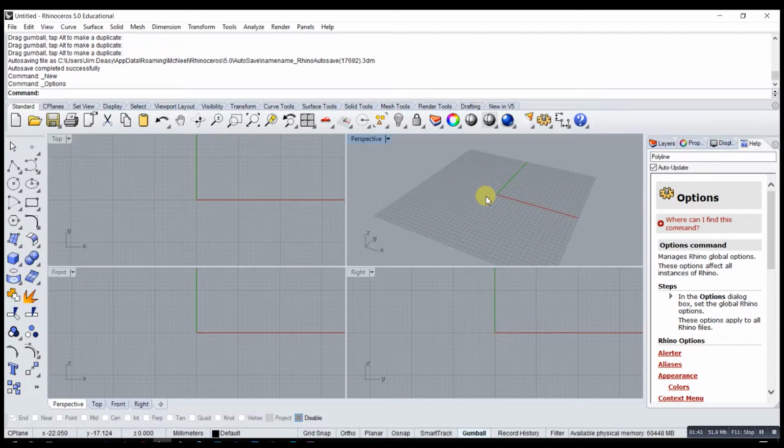The thing that can be confusing is once you start to work with other CAD packages, like once I start getting into SolidWorks and so on, rolling around in 3D like this is going to take a different set of buttons on the mouse. In SolidWorks, it's the middle mouse key that allows you to toggle and dip around in 3D. But here in Rhino, it's the right mouse button. As you flip back and forth between both programs, it can be difficult to remember which one's which, and there's always a little learning curve. So Rhino, it's the right mouse button.